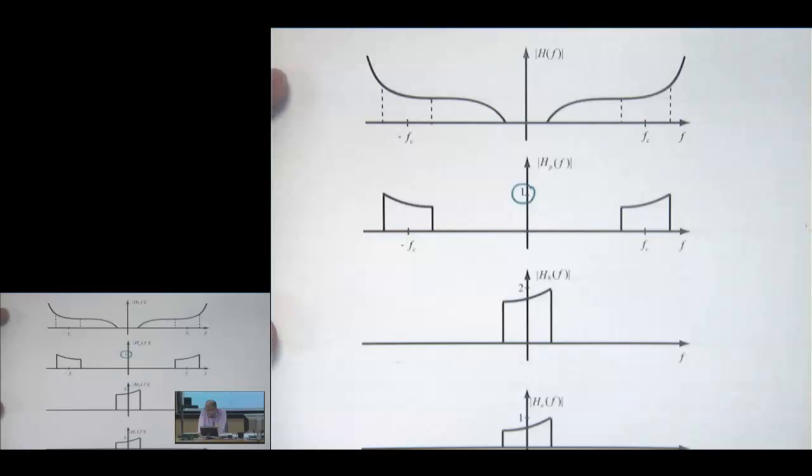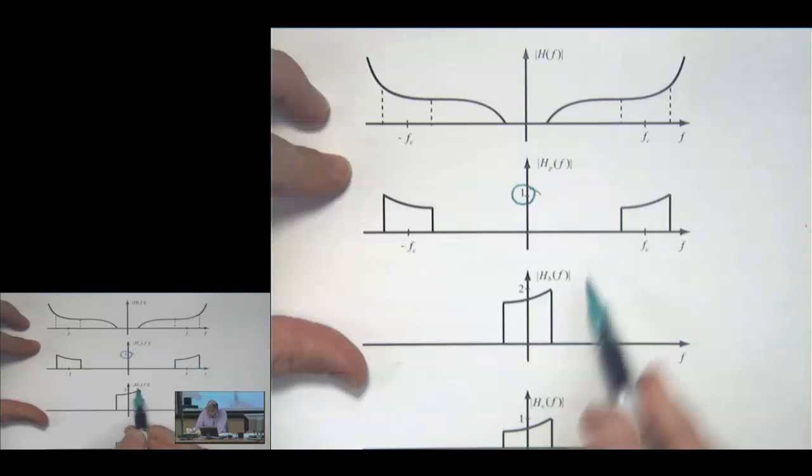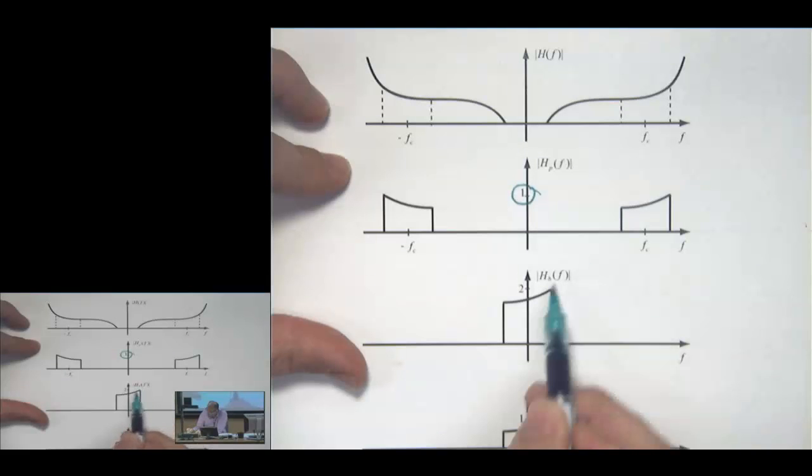Remember from the previous lecture that when we go from baseband to passband, a factor of 1/2 comes in. So the spectrum is like 1/2 X_B(f minus f sub c), plus whatever. There's a 1/2 in there. But here, look, we're starting off in the passband world; we didn't start off in baseband. So when we go to the baseband equivalent channel, which is H sub B here, we pick up a factor of 2.